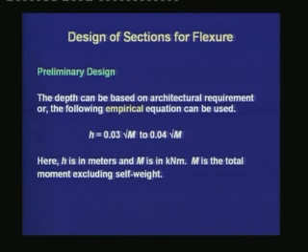The depth can be based on architectural requirement, or the following empirical equation can be used. H is equal to 0.03 root over M to 0.04 root over M. Here H is in meters and M is in kilonewton meters. M is the total moment excluding self-weight.